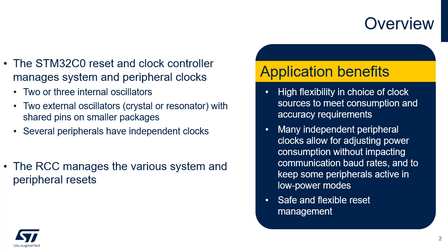The STM32C0 Reset and Clock Controller manages both system and peripheral clocks. STM32C0 devices feature 2 or 3 internal oscillators, depending on the device, and 2 oscillators for use with external crystals or resonators. Notably, there is no PLL in the STM32C0 series. Many peripherals have their own independent clocks. The RCC also manages various resets within the device.